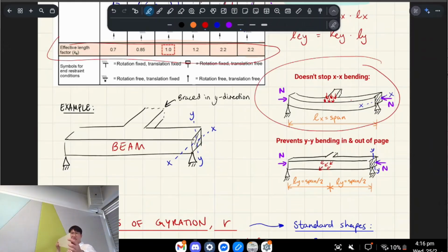And it's doing x-axis bending, like down. It might be not braced. As it bends, it does a full C shape down, right? But if it bends in and out of the page, it might be braced in the middle, because usually bracing is there to support the weaker direction. Do you get what I'm saying?